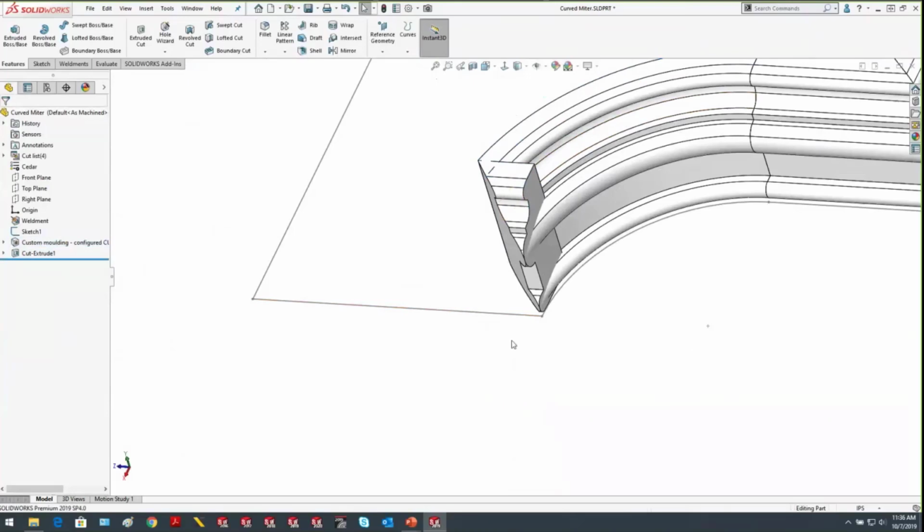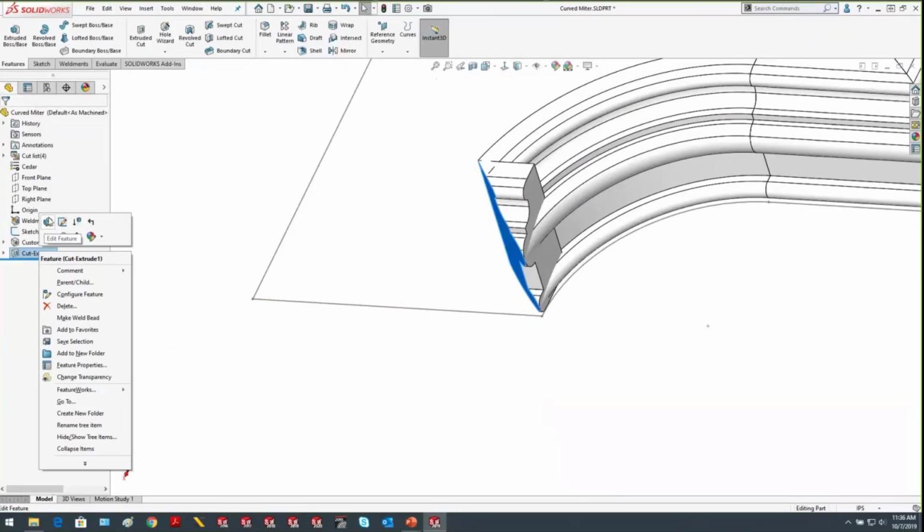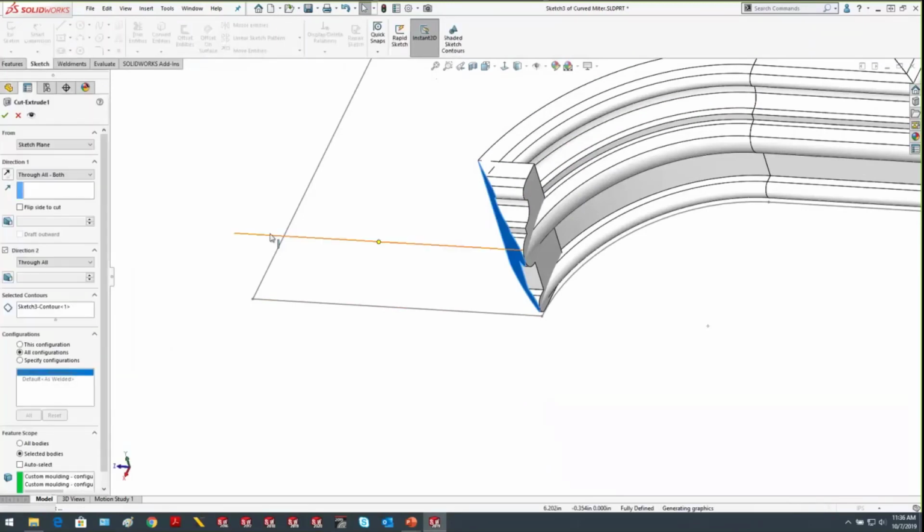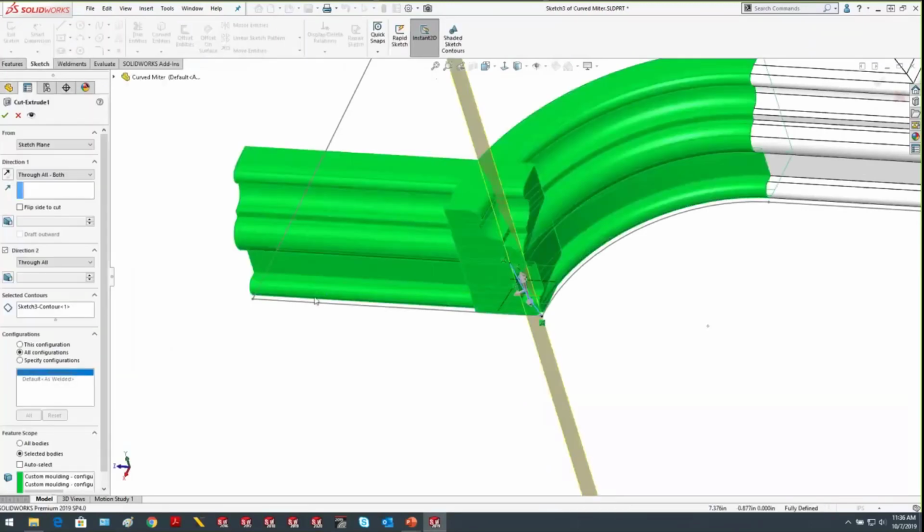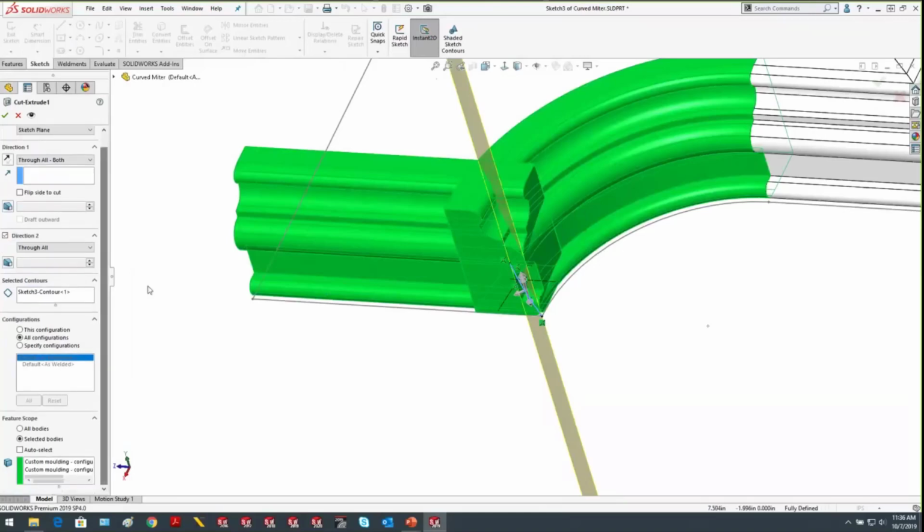So this is going to be the last tip that I have for you as far as weldments go, and this is a great tip to use because it's specific to multi-bodied parts. And that's great for weldments because that's exactly what weldments are. They are multi-bodied parts. So anytime you're dealing with a weldment or a multi-bodied part, whenever you create a feature, if you scroll to the bottom of that feature, you're going to have a category called feature scope.